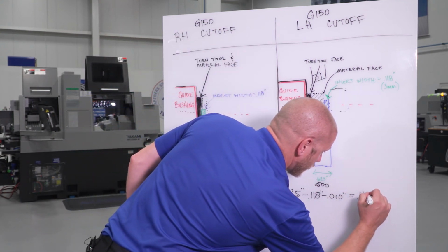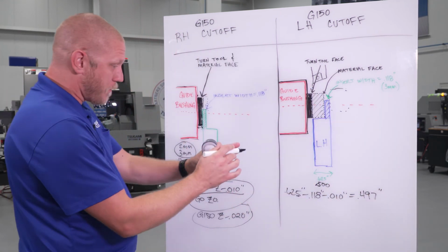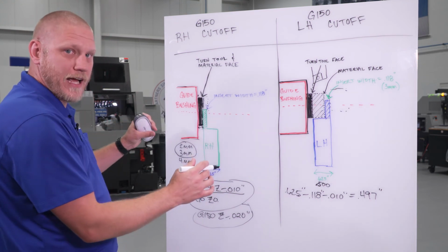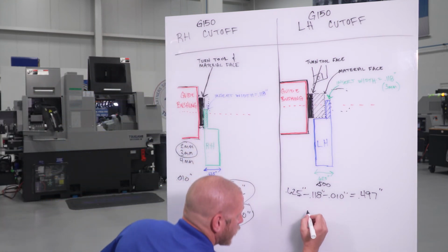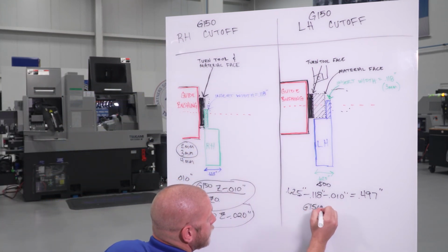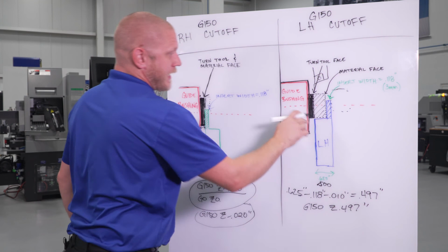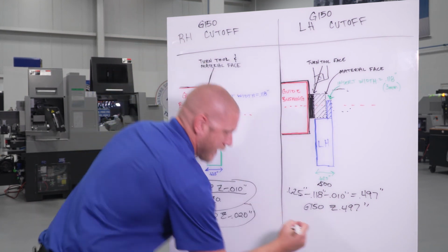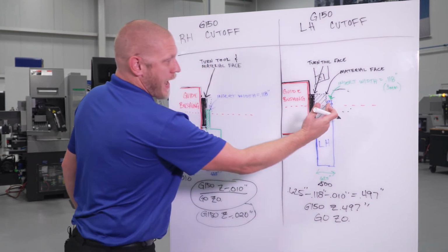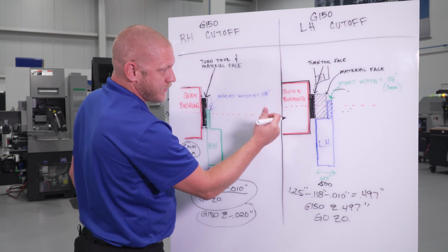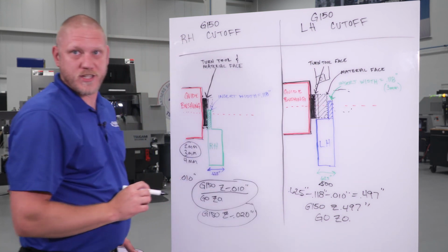So we're going to tell this, where is my Z1 sitting right now? After I opened my collet, retracted my main spindle, and clamped my collet again, where is this face? What do we want to call that? We would want to call this G150 Z.497. That means we're sticking out a positive .497 right now. So now when I say let's go to Z0, it's going to back up in the negative direction .497, leaving 10 thousandths sticking out for the turning tool to face off.